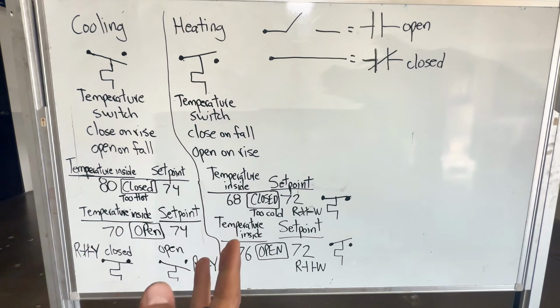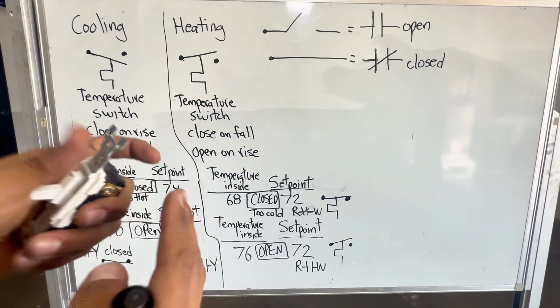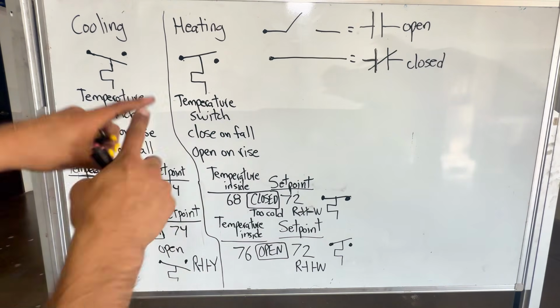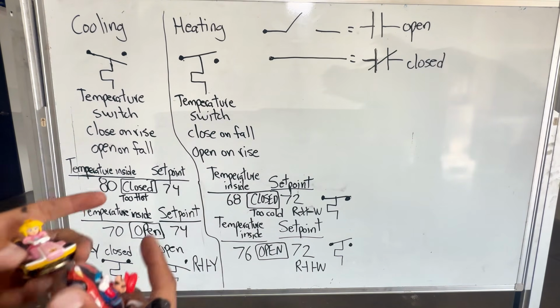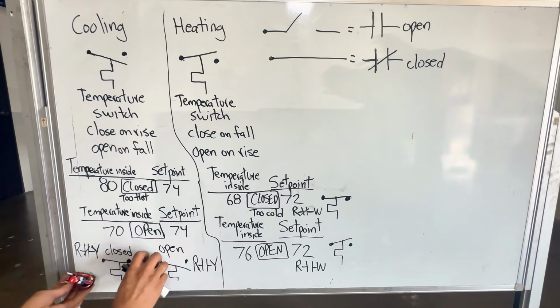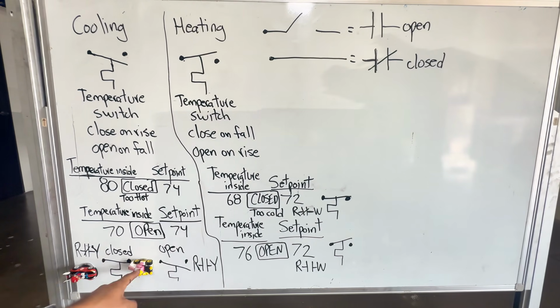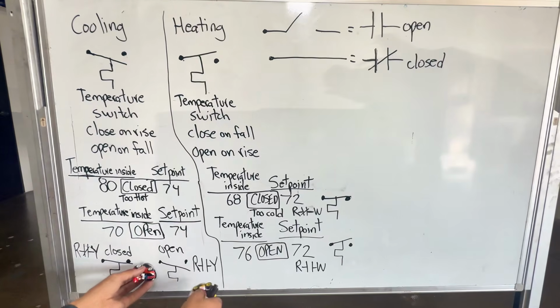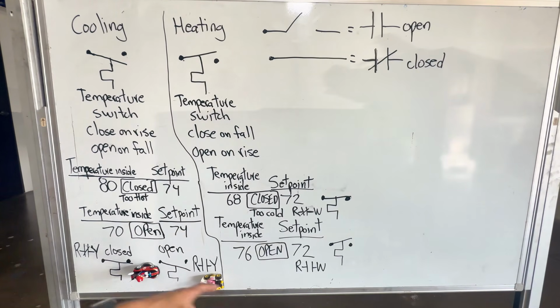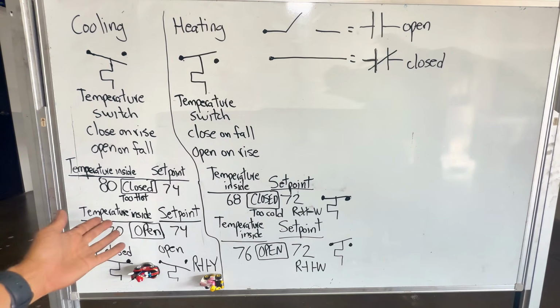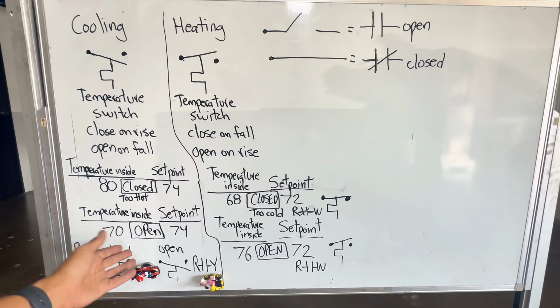But do you understand the concept here? It's just a switch. That's all we're doing. It's all a switch. In all these scenarios here, based on temperature, either we're gonna have a path, right? And in this case, it's R and Y, Mario and Peach. If it's closed, boom, I have a call for cooling. Great, I'm happy. But if it's open, there's no call for cooling because it's open. I'm already satisfied in this case.